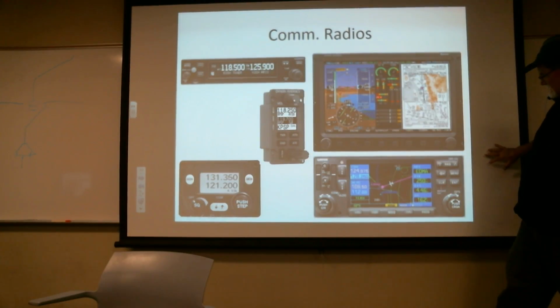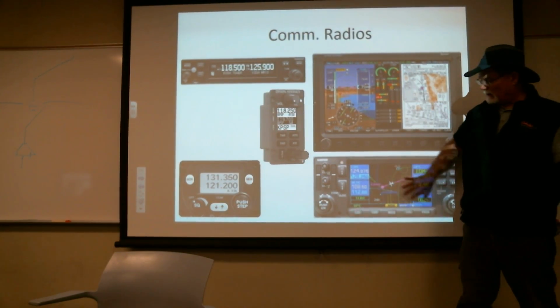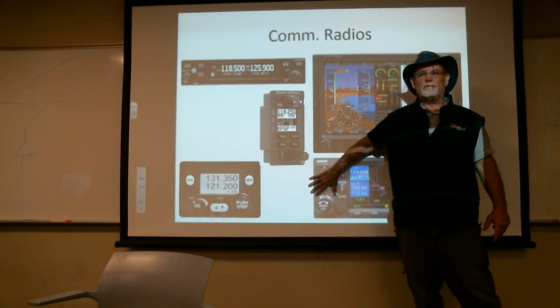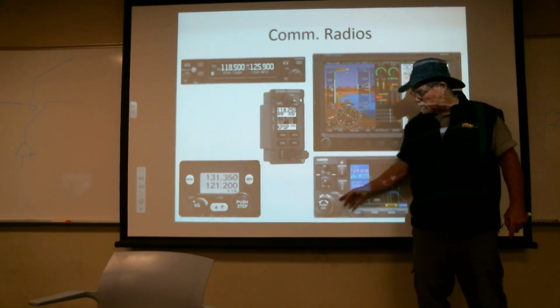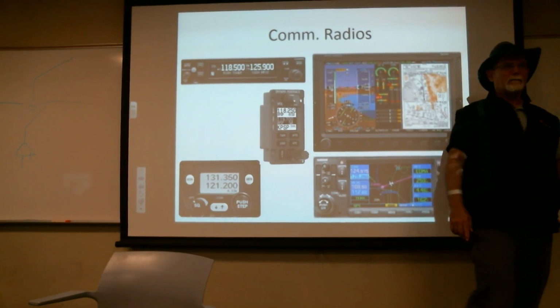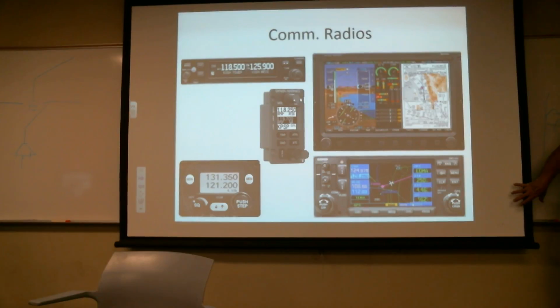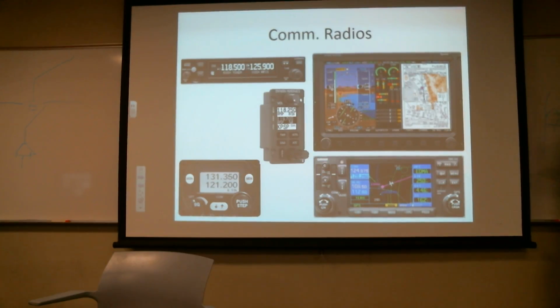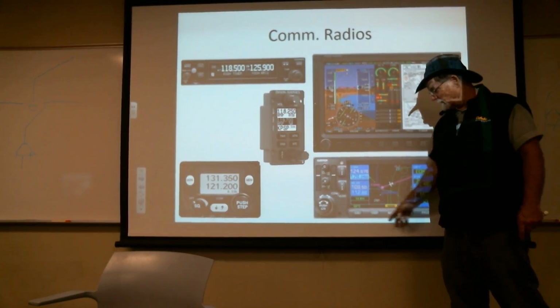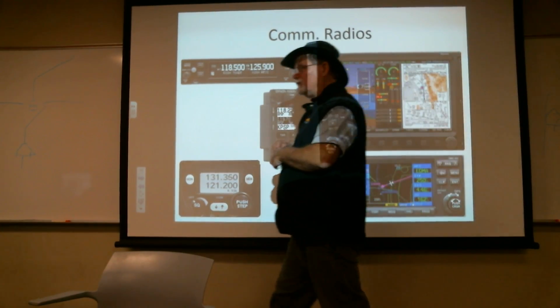Is this the 530, I think? No, it's the 430. This one, we've sort of said navigation here, map and all this kind of stuff, common VOR stuff here. So all my comm frequencies and flip-flop are going to be here and stored here, and VOR ILS navigation stuff displayed here. However, this will provide all the nav data. I'm going to need a separate display for the instrument that shows my ILS VOR glide slope data. This display is going to give me all kinds of map view, as well as GPS data.